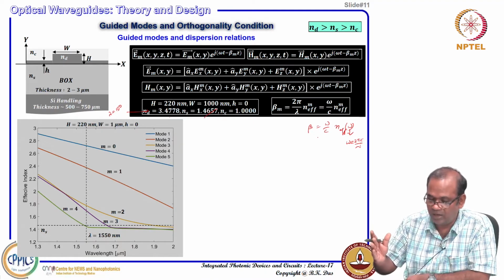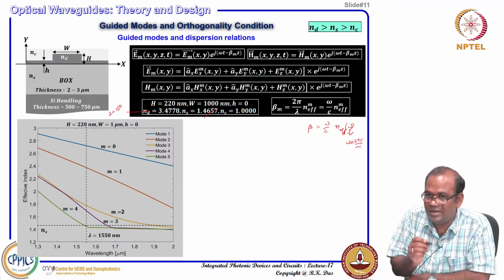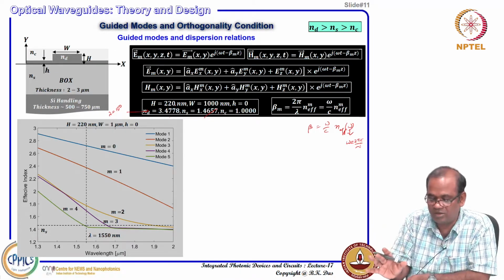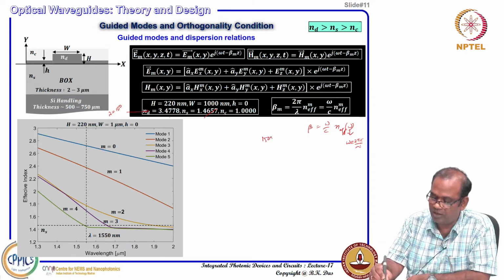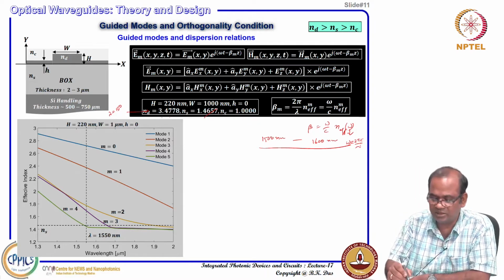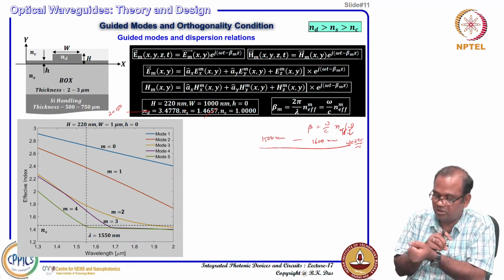If you sweep the lambda to see all the solutions, we need to know the lambda dependent refractive index of the material, the material dispersion. But in this case we have considered that the material dispersion is almost 0. There is material dispersion, but for the present discussion we have considered it to be 0. Because you consider 1500 nanometer to 1600 nanometer, a very short range, within that range the refractive index change may be very minimal. But whatever is there, you must consider, of course.